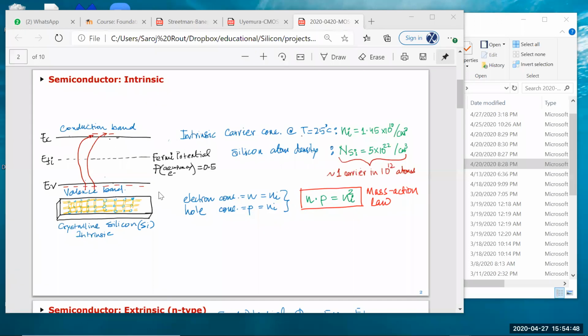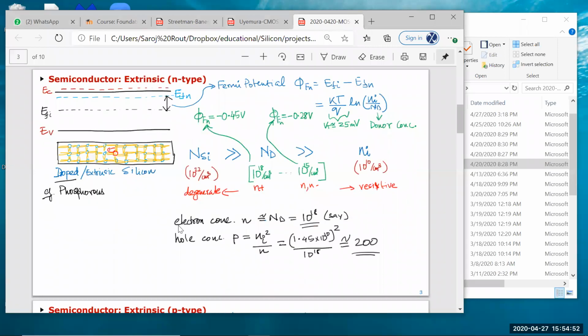Okay, so this is an intrinsic semiconductor, then we said we can dope it with a dopant which has one extra electron. And if you do that, then the average electron density potential energy increases to the extent that it is closer to the conduction band, which means that at a given temperature, like room temperature, you'll have a lot more electrons in the conduction band to conduct.